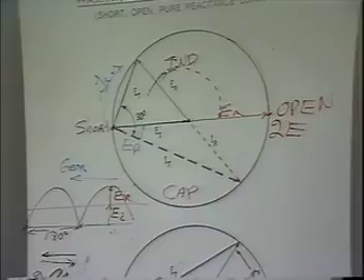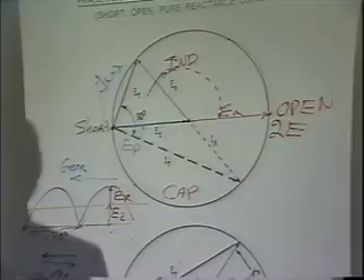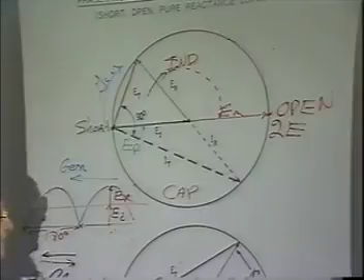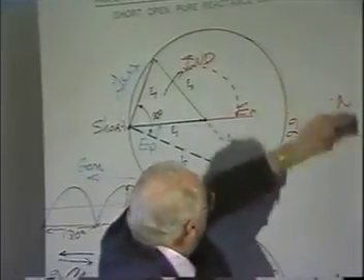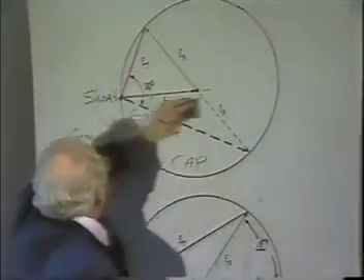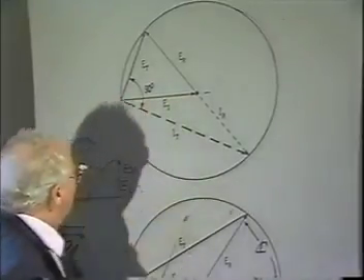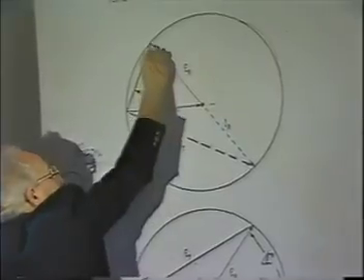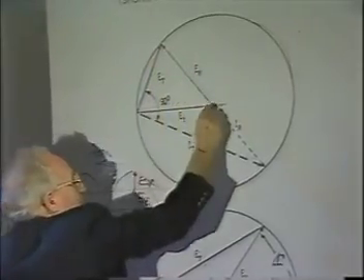In other words, if I terminate the transmission line in Z sub 0, the characteristic impedance of the line, I have no reflection, right? If you have no reflection, then what happens to all this stuff up here? If I have no reflections, this E sub R is 0.